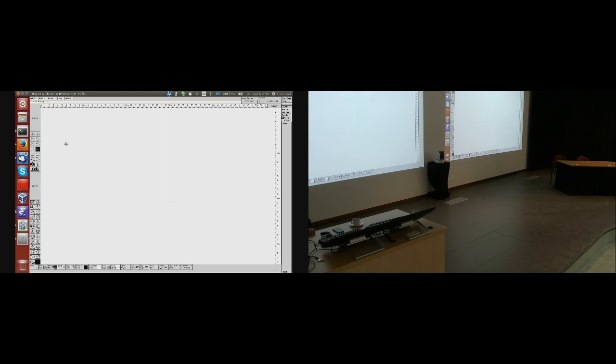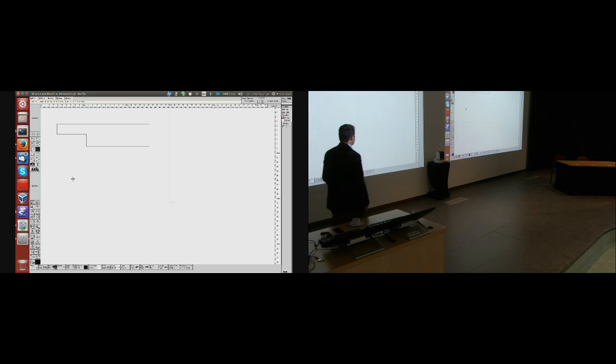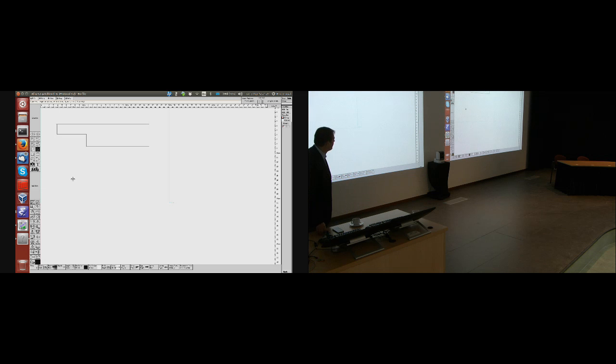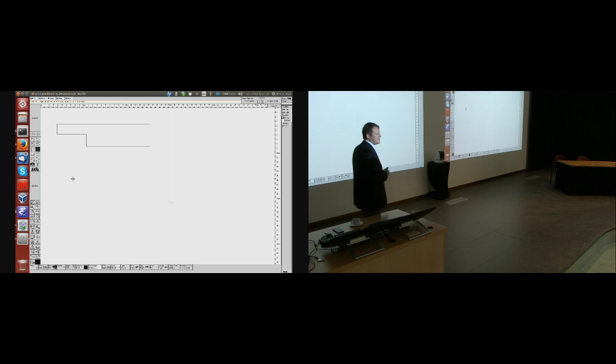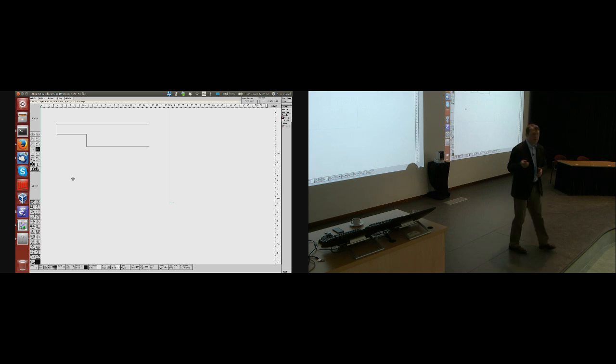Okay, so what I want you to do is to create me a geometry that looks like this. And it is a backward-facing step. The flow will come from the left-hand side. It will come out of the right-hand side. The top and the bottom patch will be zero. Okay? So what I expect to have is a recirculation region somewhere around here with the flow going around.